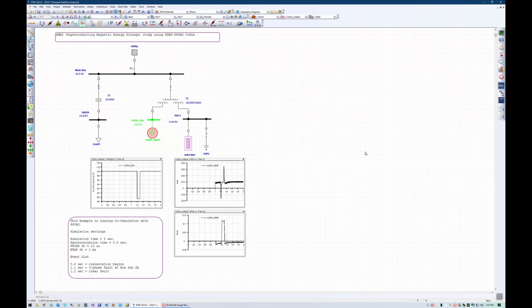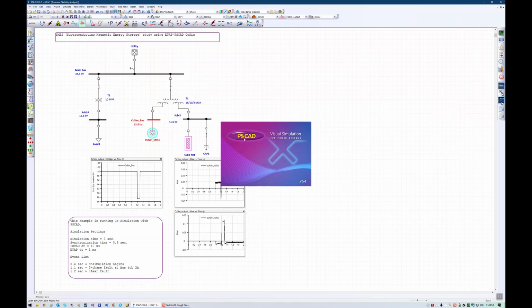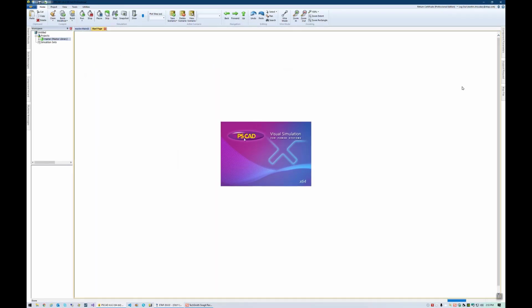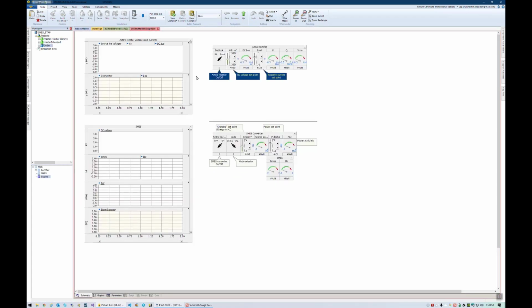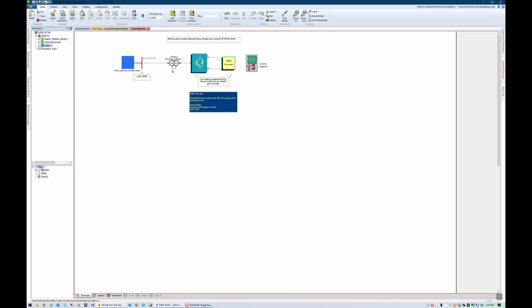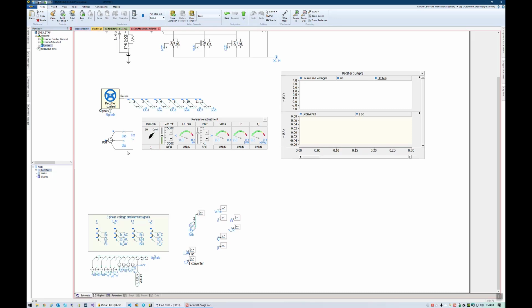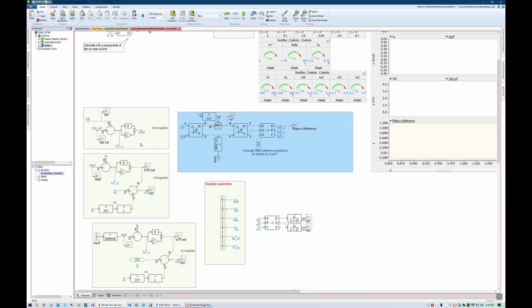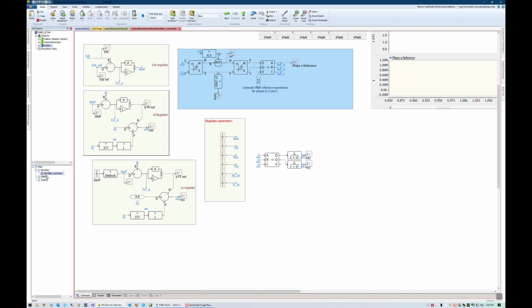The next step is to set up the electromagnetic transient domain using ETAP eMTP. We click to launch the eMTP editor. In this case, we have already defined an energy storage converter which is modeled with a rectifier. The converter is enabled at 0.3 seconds and includes 2 sets of controllers, one to maintain DC voltage and another one to charge and discharge the inductor. Reactive power control can also be set up by means of a PI controller.